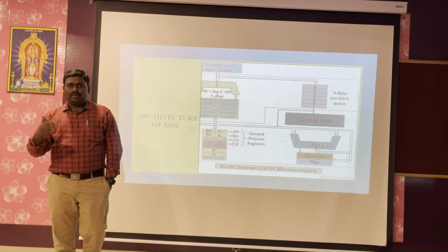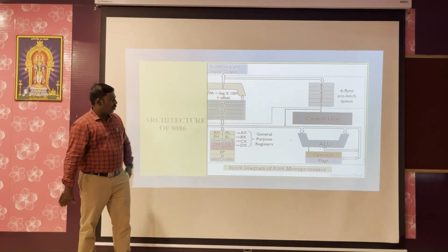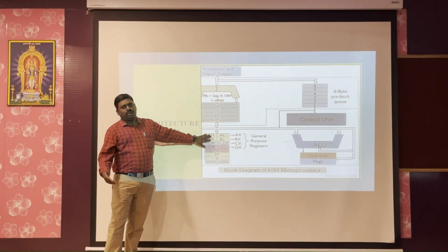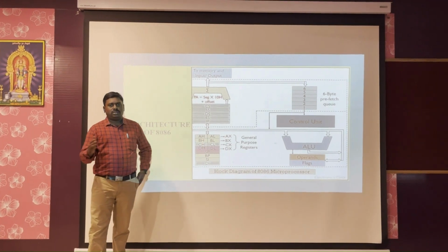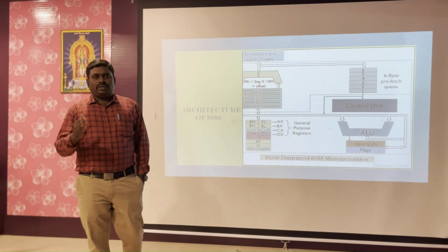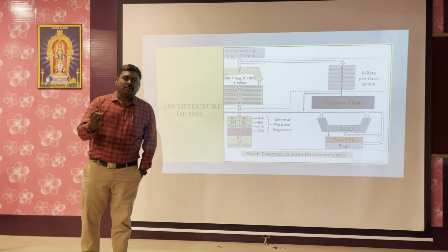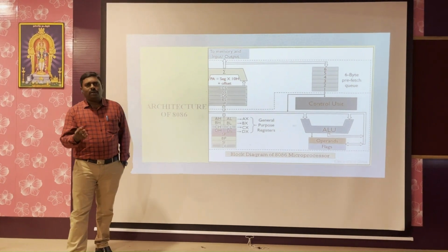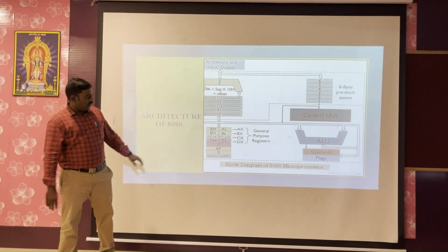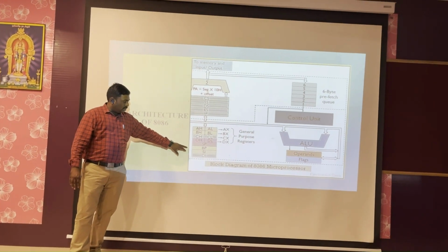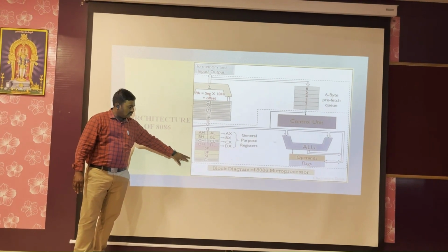For example, if you take 8-bit, then one of the registers may act, that is AL or AH. So the general purpose register is the combination of two 8-bit registers, which is nothing but AX is the accumulator, BX is the base, CX is the count, D for data. Okay, these registers will be used. Followed with stack pointer, base pointer, source index, destination index.